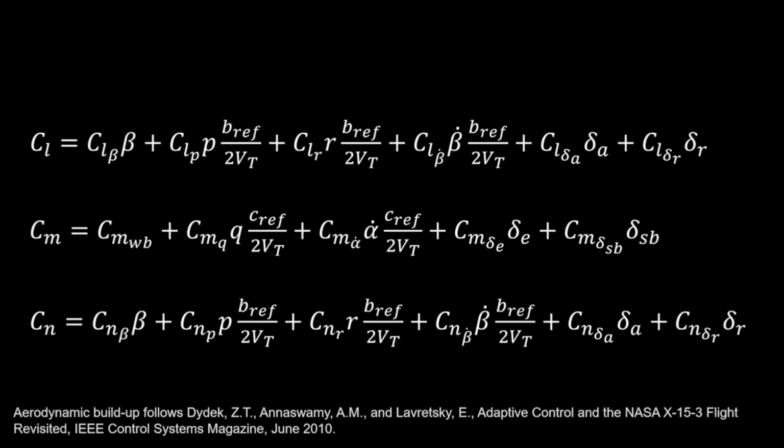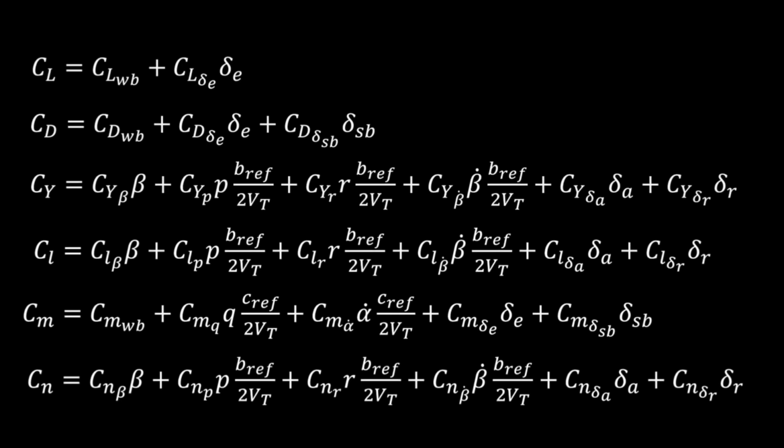In our build-up, we're going to ignore the acceleration derivatives, that is, those derivatives of angle of attack and side slip. Often, these are ignored in aircraft. Placeholders for these derivatives exist in our simulation and may be included in later updates.